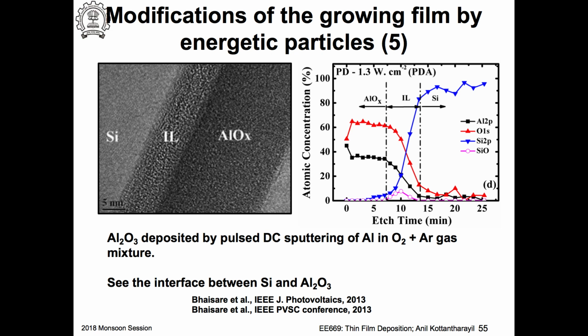I should know, in each sputter step or etch step, how much material is removed. That is a little bit difficult to find out because the sputtering yield of aluminum oxide, silicon and these layers could be different. So, typically you do this if it is a homogeneous material. I can easily translate this into an etch rate, meaning I can find out the etch rate from which I can translate this into a depth. But it gives you what is called a depth profile, though this axis is not the depth.